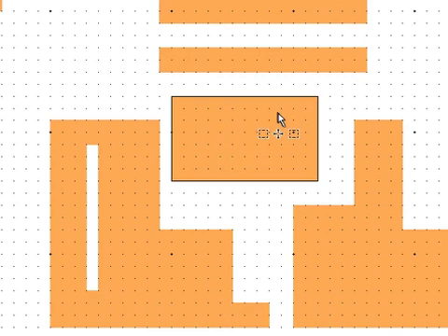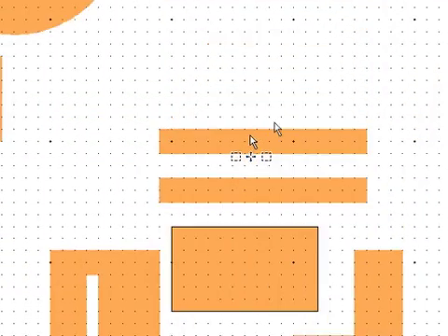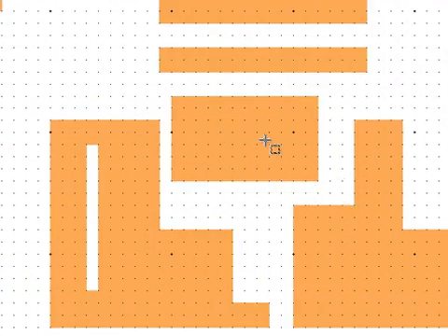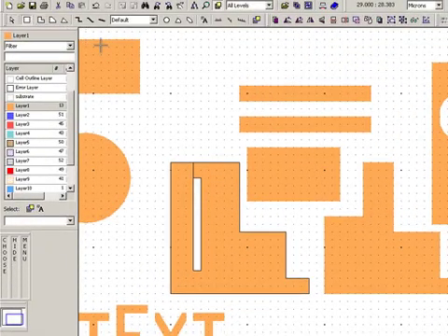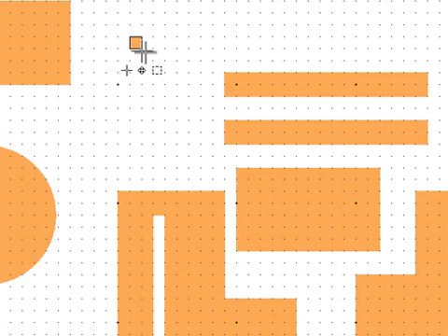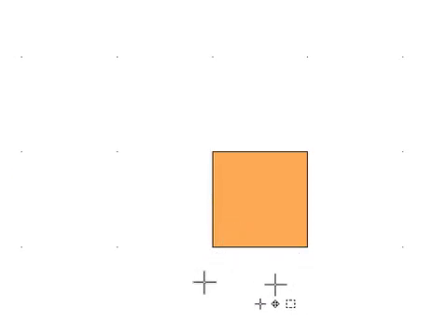And one thing that can sometimes cause a problem is when you're working with small cells, for example, something that might be 1 micron by 1 micron. When I work with a really small cell like that, basically the threshold for moving and editing is 1 micron. So as I select this, now you see there's nowhere in here that I can actually move this. Anywhere I click my middle button, I'm actually editing that object.